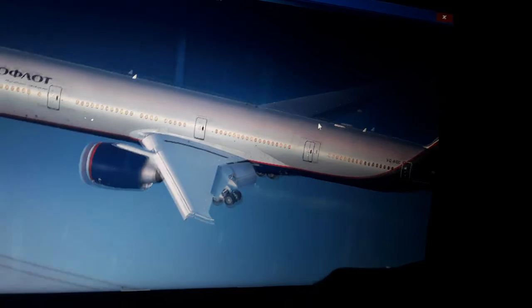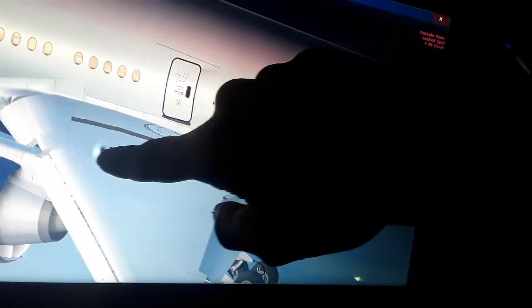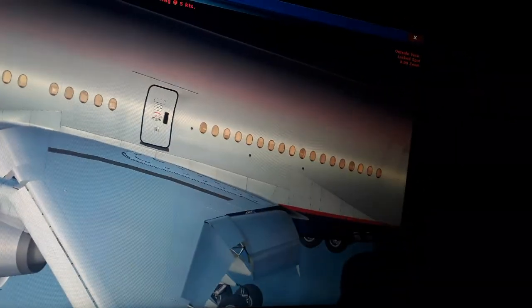Also this is the position where the center of gravity usually is positioned, at, forward of, or aft of this position. So it makes the aircraft forward center of gravity or aft center of gravity relative to the position of the aerodynamic pressure in the forward wing. Sometimes it's exactly positioned in the same section. So you can see here we have the mean aerodynamic chord position, 35% is about here. So this is the maximum lift position.